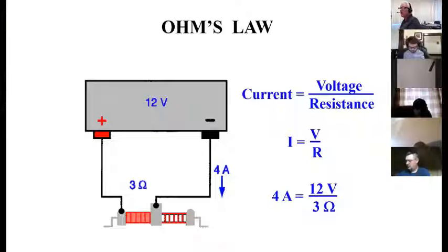All right, so all this stuff we've been talking about, this relationship between voltage, resistance, and current is Ohm's law. Ohm's law expresses that in an equation. Now, I tell you that when you're doing technical work, you don't necessarily have to come up with very precise numbers. Most of the time, you just need to be in a ballpark. If I'm looking at a circuit and it says on the drawing that it's supposed to be 9 volts, but when I put a meter on it, it says that it's 8.85, that's probably not what's causing the thing not to work right. Usually you're going to see like the voltage is going to say nothing, or 2 volts when it's supposed to be 9.